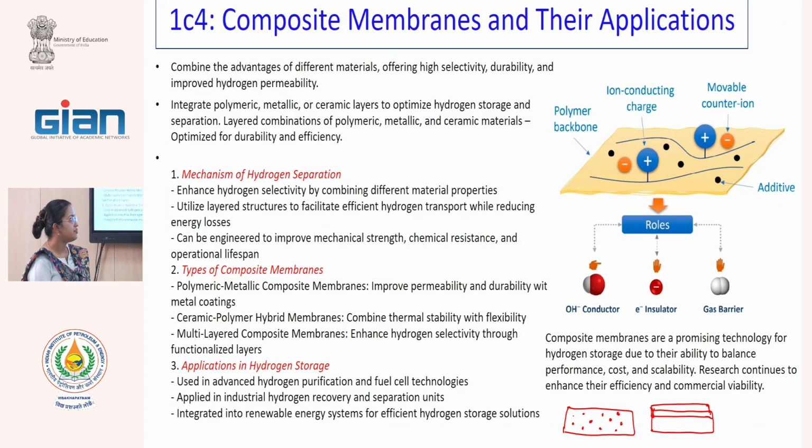They are very popular additives of choice. So, they are inserting those into this material. Now, yesterday I was talking with you about the water channels. What these additives are doing is that they are not letting these water channels collapse at higher temperature. So, you can enhance the thermal stability of the membrane by incorporating this kind of additive into your system.